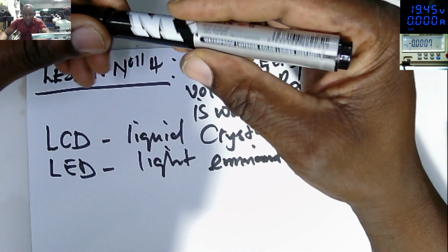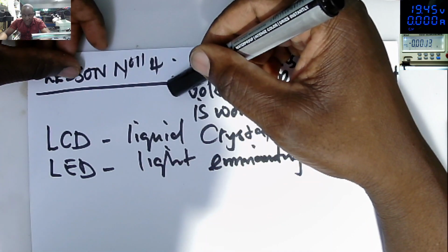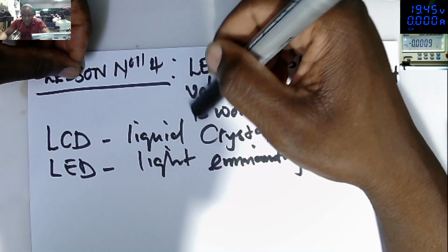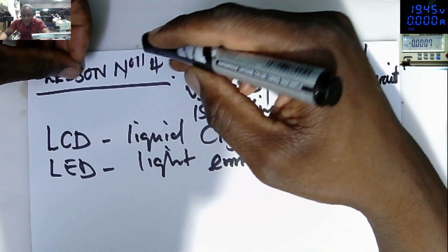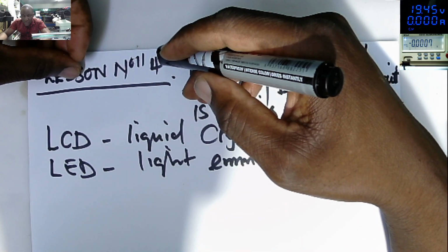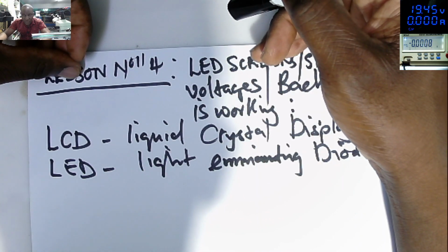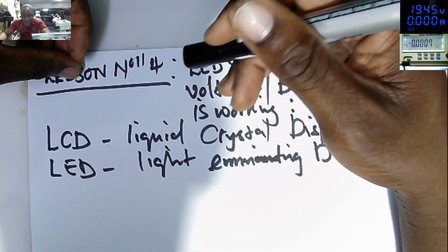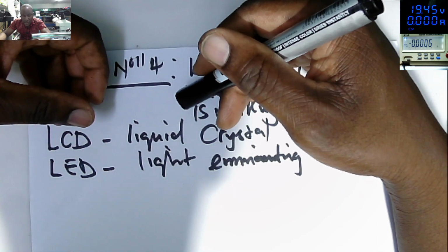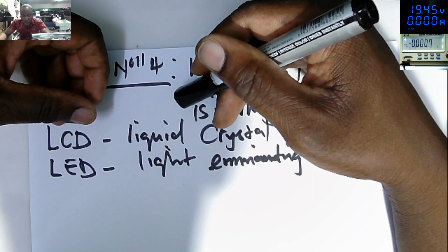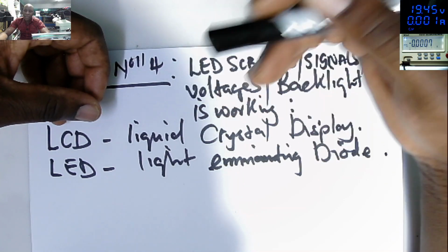So we have to understand how laptop screens are working. When you press the power on button, the startup chip or the microcontroller is reading all power supplies and everything on the motherboard. If the motherboard passes the test, the processor and the GPU will respond and will send a signal to the screen, and in that way we have a picture and light on the screen.